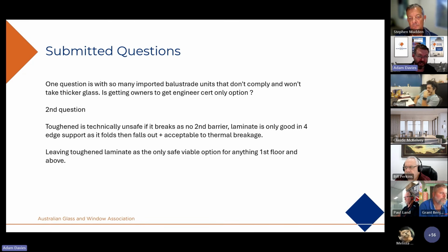Conventional laminates, yes, they are not sufficiently rigid, but specifically there are higher performing rigid interlayers that are appropriate and more than safe. And in fact, if they are selected in accordance with 7.46, they are actually a little bit more stringent than what could be inferred with an interlinking handrail barrier, as the SLS load is done in a semi-failed fashion with one layer broken.